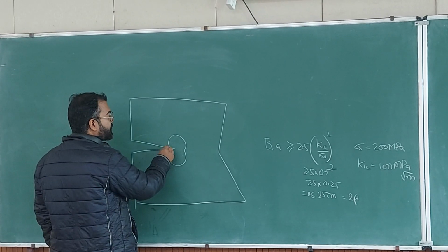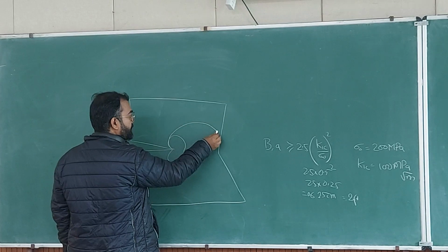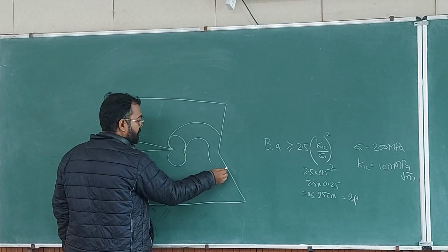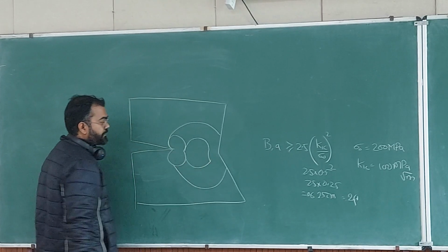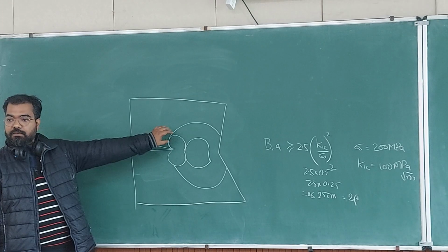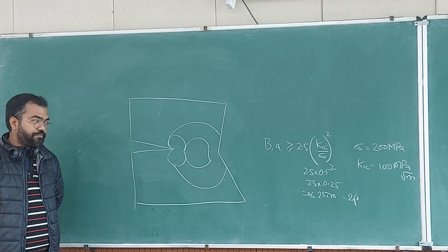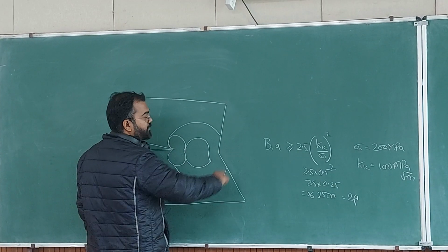so if you keep on increasing stress, then this plastic zone will increase, and then you will have a plastic zone like this. So this whole area inside the two lines will be plastically deforming. It will not be that everywhere you have plasticity.